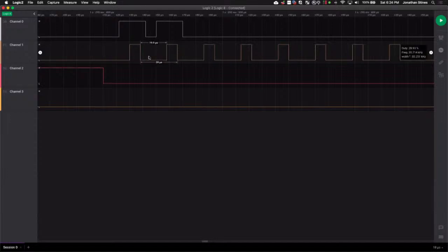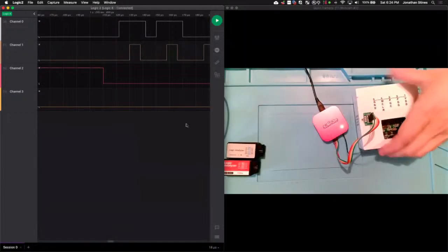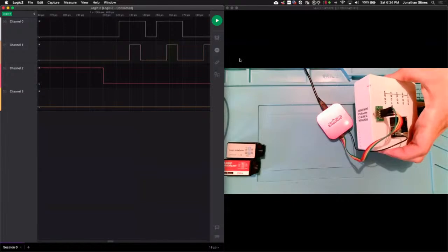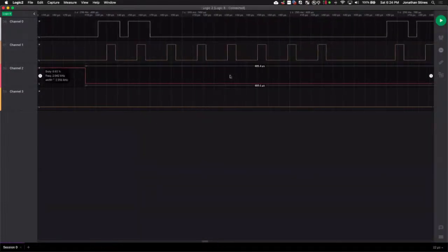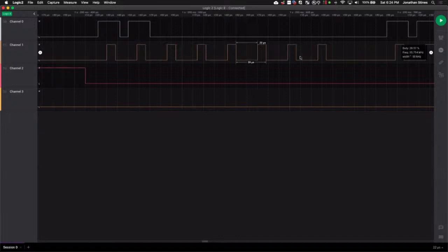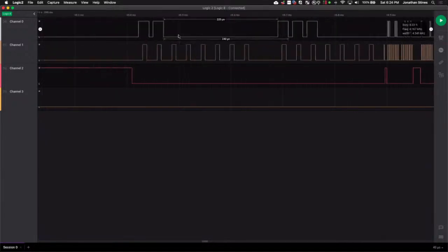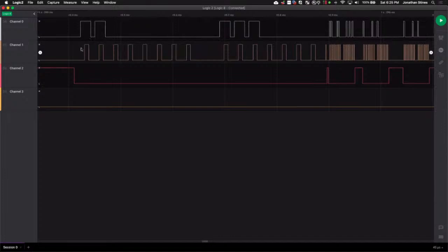We also see right here, channel 1. Channel 1 in this case is clock. Remember, clock is going to actually set the cadence for how it communicates. 1, 2, 3, 4, 5, 6, 7, 8. It's a full actual byte of data. That's pretty telltale. So right here, of course, channel 0, we have some type of sporadic data being set. Channel 1, we have kind of a constant cadence of information in the waveform itself.